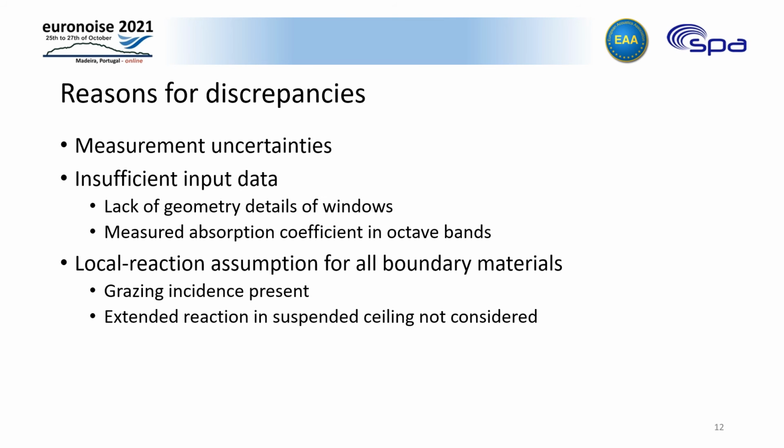Lastly, the current wave-based simulation models all surfaces as locally reacting. However, for the considered office, grazing incidence might be more pronounced in the early reflections. The suspended ceiling has a large air cavity behind it, which may exhibit strong extended reaction.